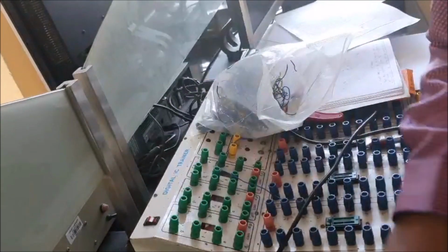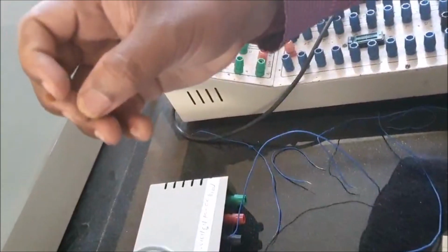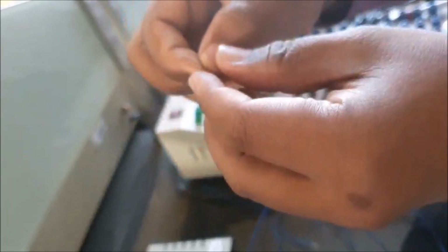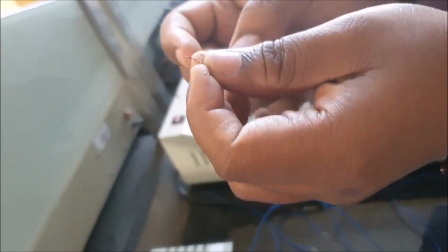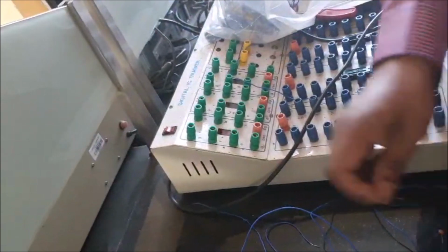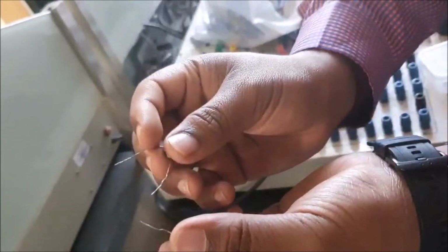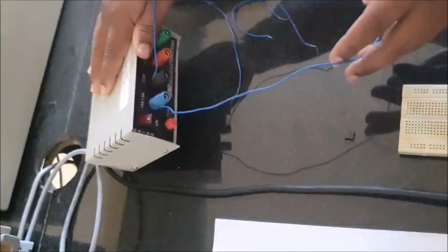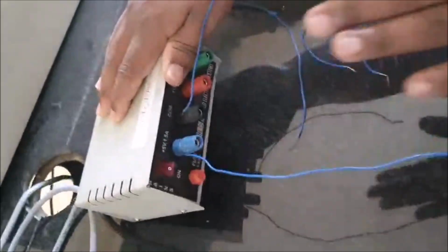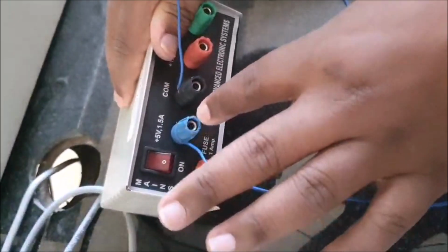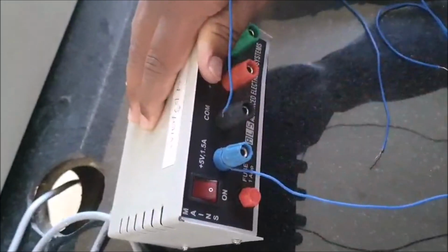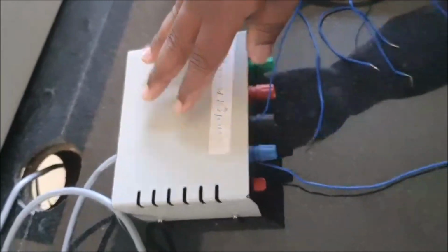And also we need 3 capacitors. The bigger one is the 0.1 microfarad capacitor, and the smaller one is the 0.01 microfarad capacitor. Both capacitors have 2 pins, so there is no polarity. Even the resistors have 2 pins, so there is no polarity for the resistors. And we need a DC power supply. Here we need to supply 5 volts to the circuit. I will be using this DC power supply. The blue colored pin is 5 volts and the black colored one is the ground connection. So we need to supply 5 volts as a power supply to the circuit.